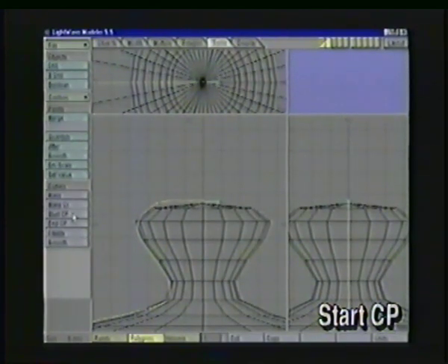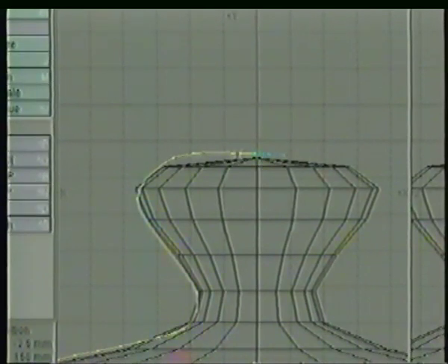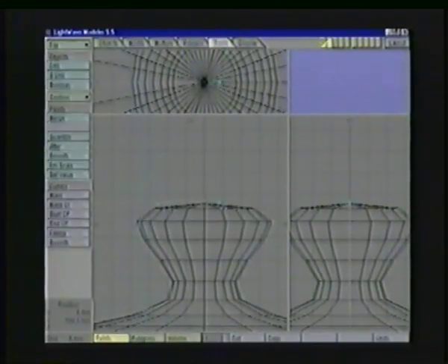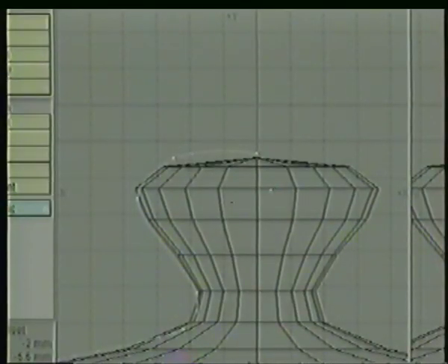By clicking on this button, the head, or start, of the curve has moved back to the second point in, yet it leaves a little dashed blue line connected to this point floating out here in space. Now if I move that point with the Move tool, you can see it still affects the rest of the curve. This allows me to get a nice smooth line across the top. I'm going to continue dragging some of these points into more of a handle shape.